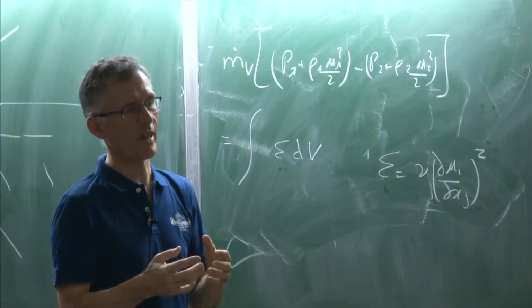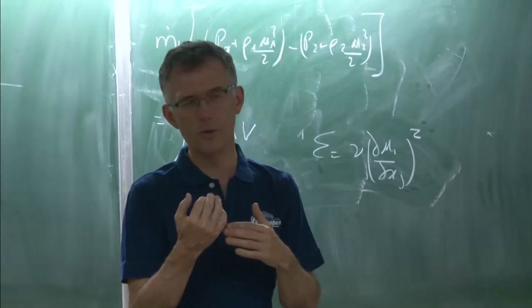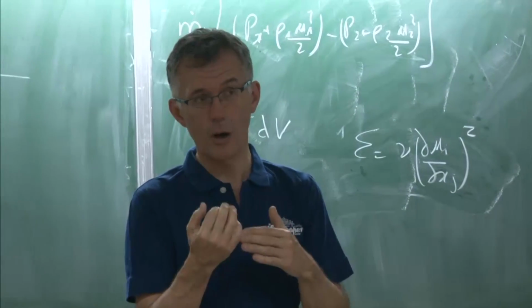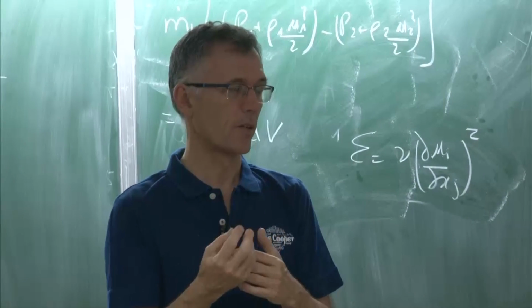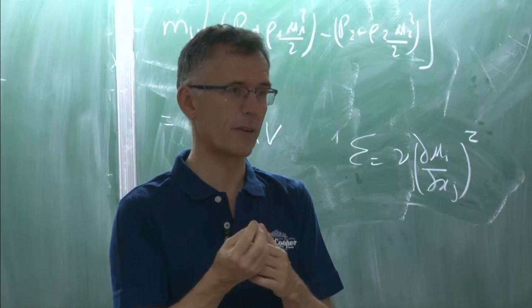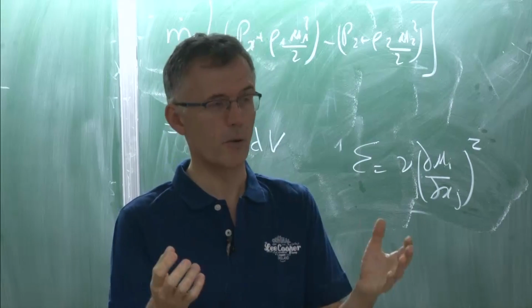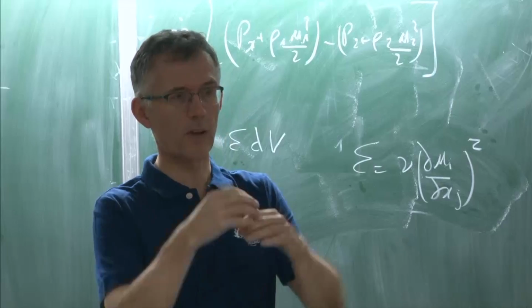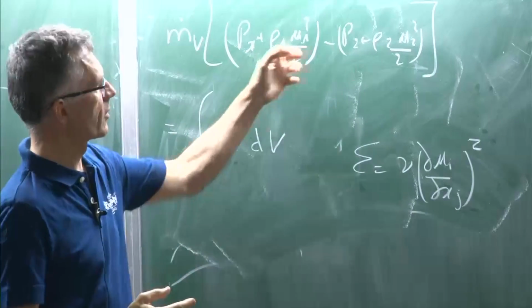It's exactly the same thing if you would like to compute a flame. The analysis will tell you that if you want to compute a flame right, what you need to optimize is not temperature or velocity, it's heat release. It's the reaction rate, because reaction rate does everything. Once you have the reaction rate in the flame, you have all the rest, because it's the source. All the rest is the integral of that. It's the same thing here. If you have epsilon, then you will get the rest right.